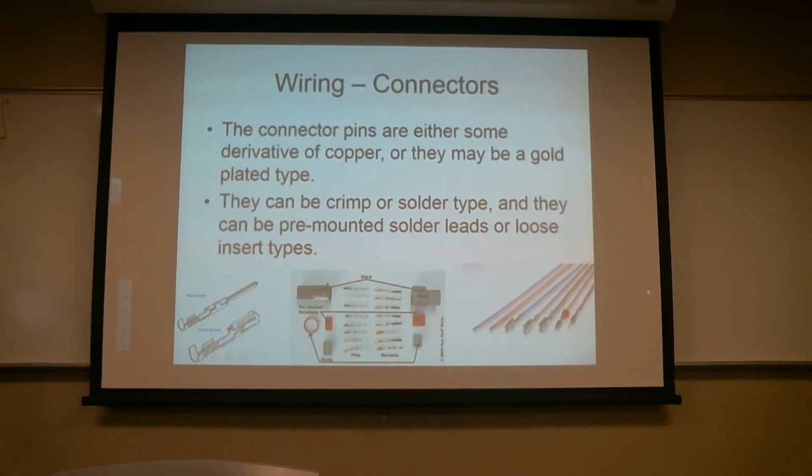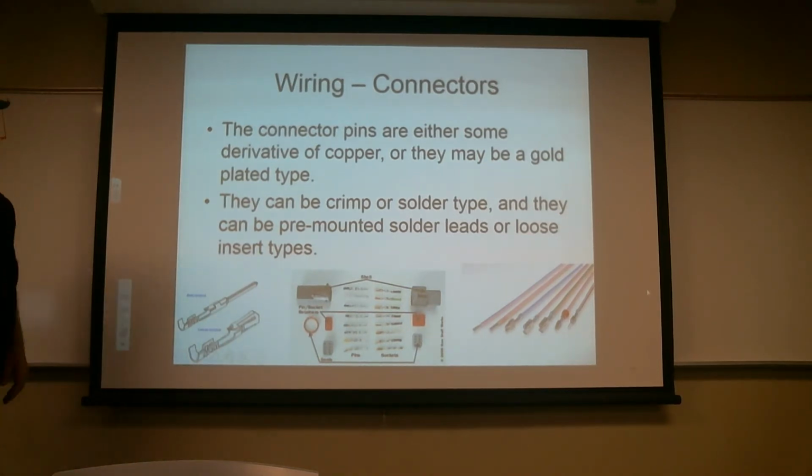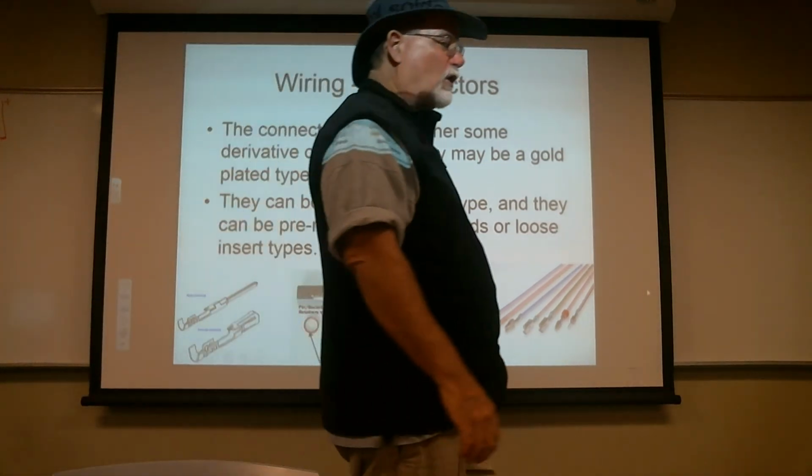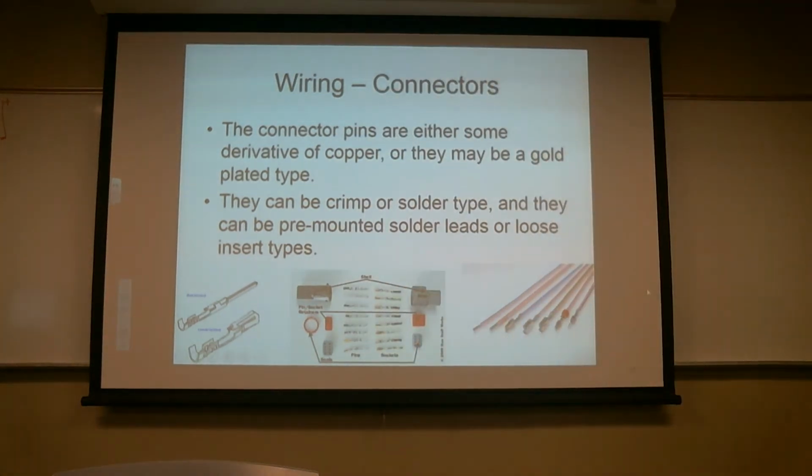They do, typically these connectors are most often tin plated. Copper that's tin plated, a little bit of tin. Tin does oxidize over a long period of time. But tin with a very slight amount of lead in it does a pretty good job of being non-corrosive. It isn't perfect. It turns out that gold sort of thumbs its nose at oxygen.